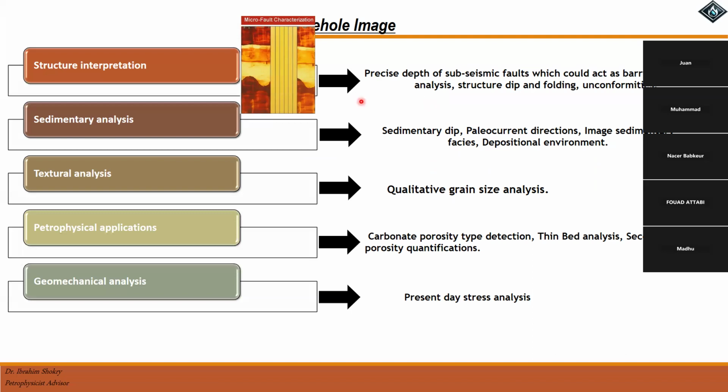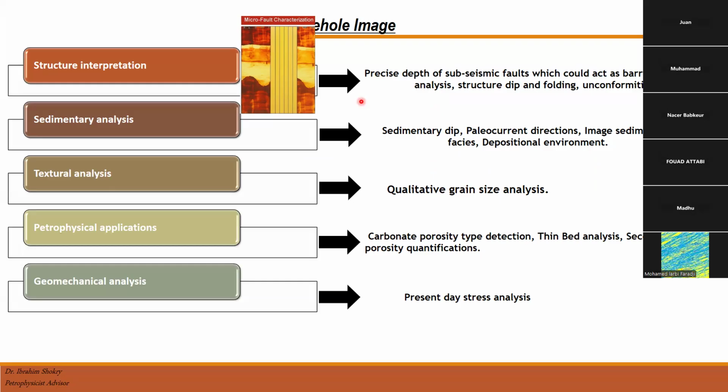If we have an actual development field with many producing wells, then after production, we run a pressure tool in some intervals. We can see in some producing layers that we have a diverted pressure. This pressure doesn't see any depletion from the other wells.